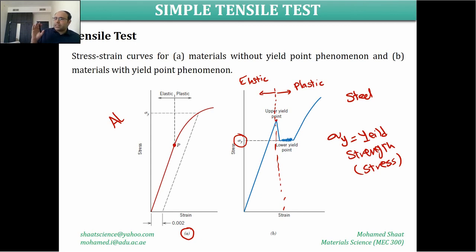It is commonly accepted and agreed in the scientific community, for people working in material engineering or material science, that the yield strength is determined at 0.002 strain of the material. What we basically do, this is equivalent to 0.2% of the original length of the material, 0.2% of the elongation of the material.